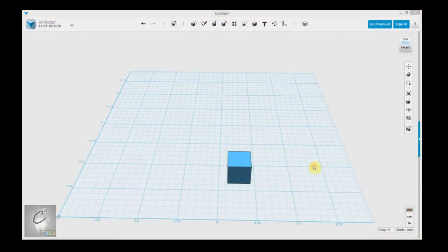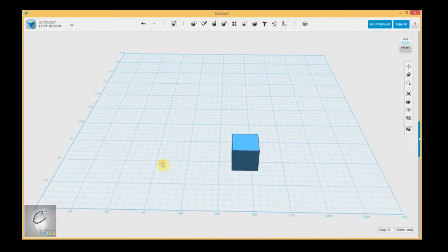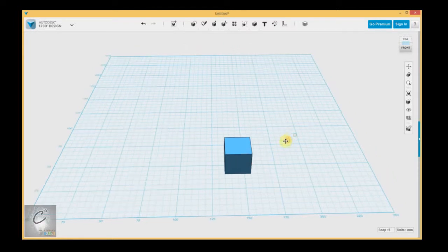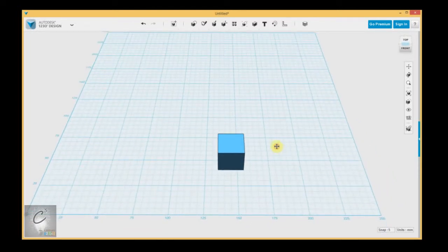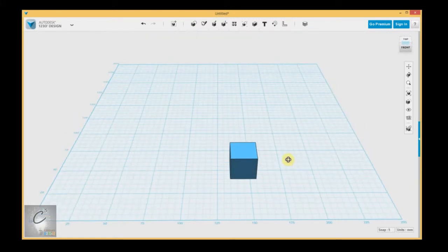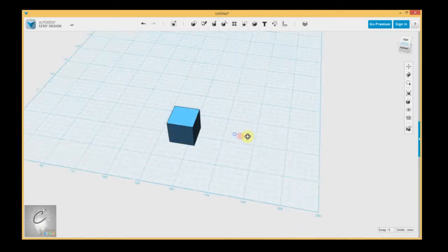If you're a Pikes Peak Library District patron and you're doing this mostly to get some 3D prints going, I recommend you design in millimeters, or design in inches and then convert to millimeters at the end. The reason is that STL files save the numbers of the measurements your object's dimensions are recorded in, but they don't actually save the unit.